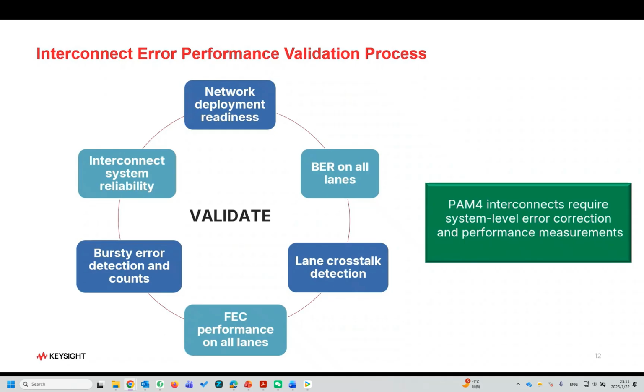And then we have to do interconnect system reliability under stress, over temperature ranges, with stressful traffic, both BER, PRBSQ patterns, forward error correction, line rates, scrambled idle traffic, layer 2 Ethernet traffic that in certain ways can be injected that are very stressful on the device. All of that has to be looked at for system reliability.